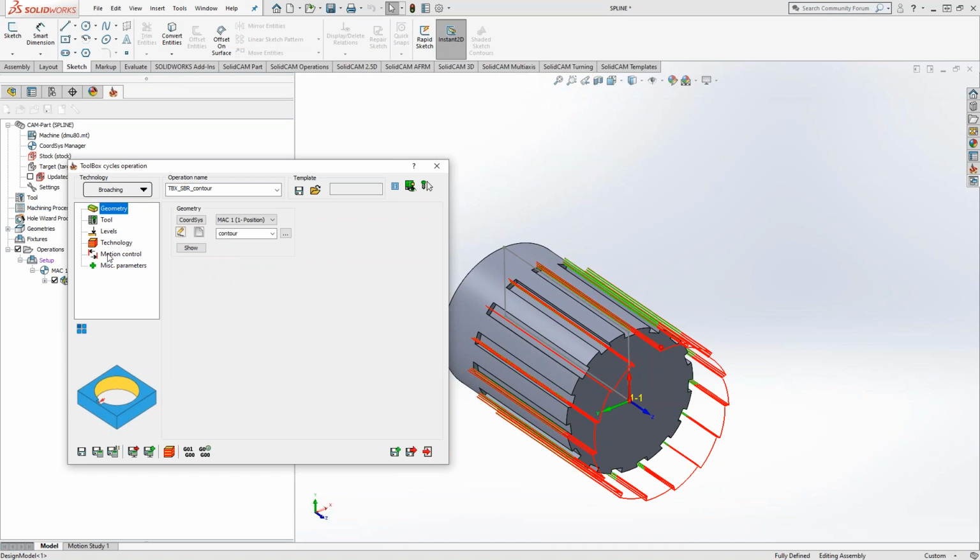But this brings up what we talked about yesterday with the manual turning, because if this is a turning tool, or literally just a tool mounted in my turret, and I define it with a certain reference point, I can get it to follow whatever chain geometry I'd like in my turning toolpath. So this broaching toolpath would require a change to your post. You would actually have to output something, or some sort of recognition in the post would have to recognize the use of a broaching toolpath and lock the spindle.